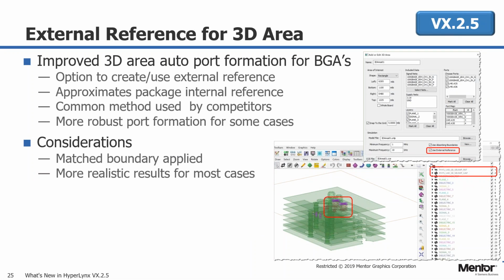Another thing to help out with the extremely high speed was getting accurate 3D models, and there was an area there where some additional tweaking needed to happen for BGA connections, and so we've improved the area export formulation for those. So that's part of the HyperLynx Gigahertz, using the full wave solver to generate the 3D models.